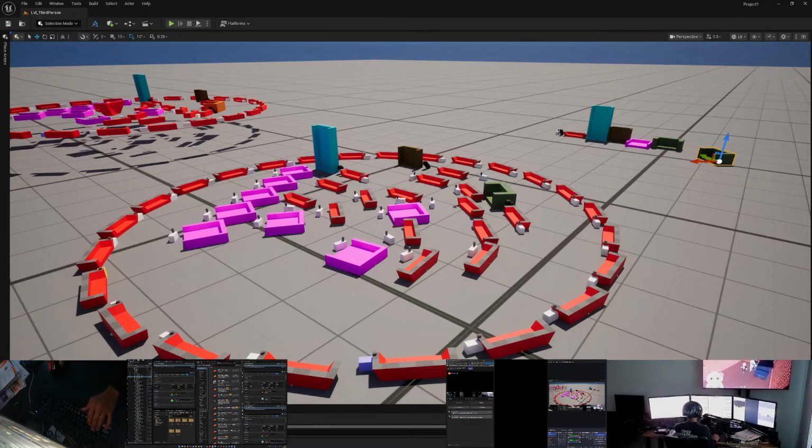Whereas I systematically set up all of my doorknobs. I bring one doorknob into the scene and change its pivot point so that if you were to twist it and rotate it to open it, it rotates around the appropriate pivot point. And forward is like if the doorknob was facing you, if you were looking at the door to pull it towards you, that would be the orientation of the doorknob in the scene. And then I would convert that to a component and then populate every other door with that doorknob.